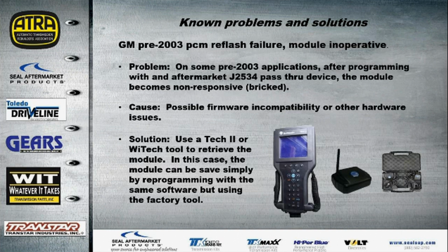GM pre-2003 PCM reflash failure, module inoperative. We get a boat anchor. Some pre-2003 applications, after programming, we have nothing. The computer becomes non-responsive. This is after we use the J2534 pass-through device and followed instructions.